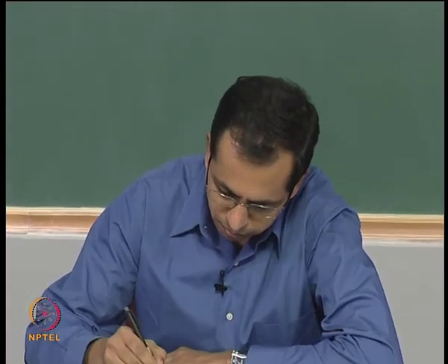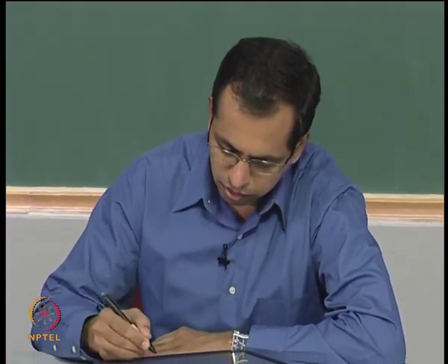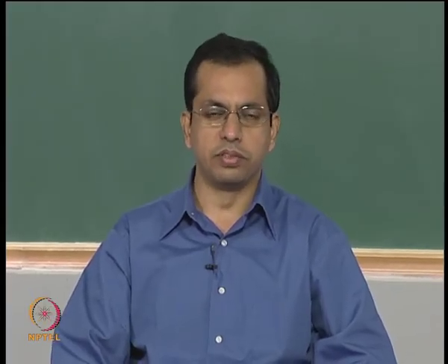Okay. So, you see that first of all the amplitude of the sinusoid has nothing to do with k. Okay. The gain has become pretty much independent of k, it is dependent only on the parameter of the integrator. Okay. And secondly, the sinusoid experiences a phase lag of 90 degrees. Okay. It is not following the sinusoid with a fixed delay, but it has a fixed phase angle of 90 degrees, which means that you can say that it is not following the sinusoid at all.